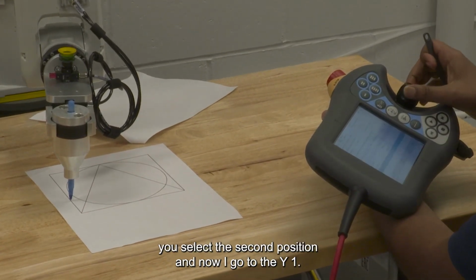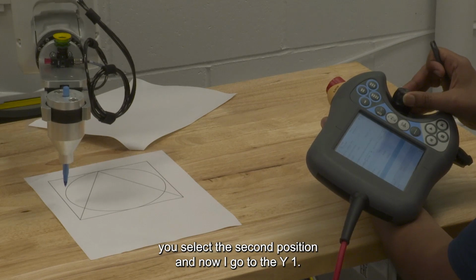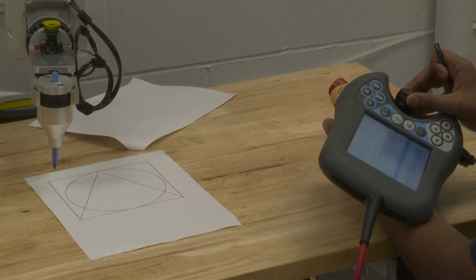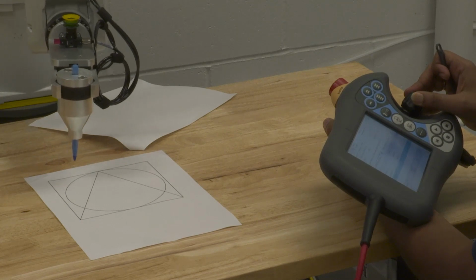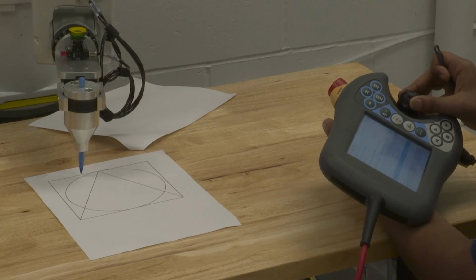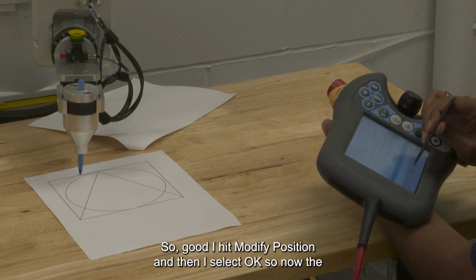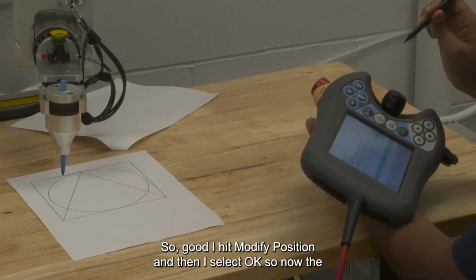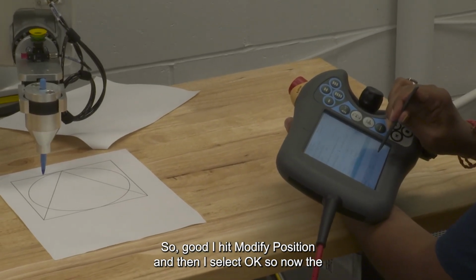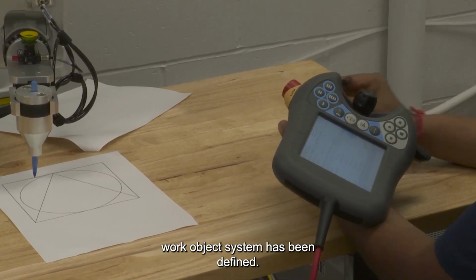I select the second position and now I go to the y1. I hit modify position and then I select OK. So, now the work object system has been defined.